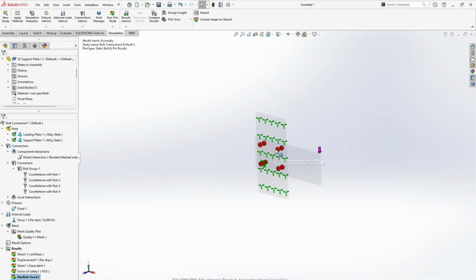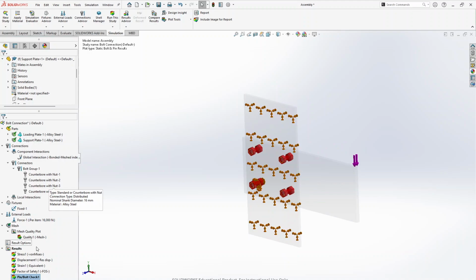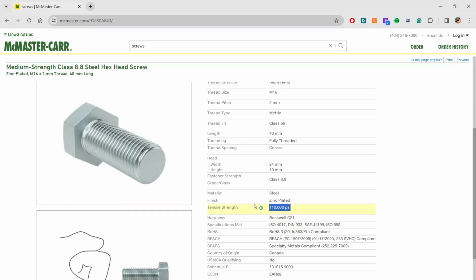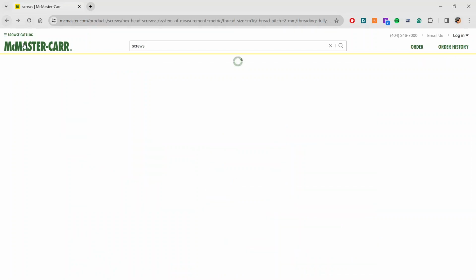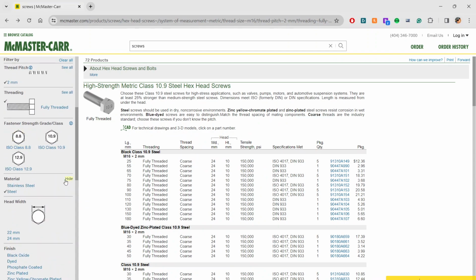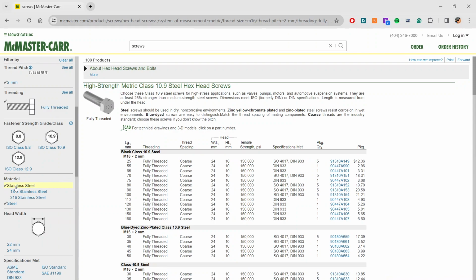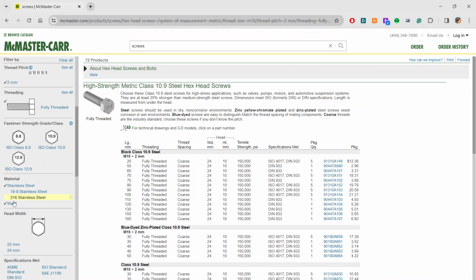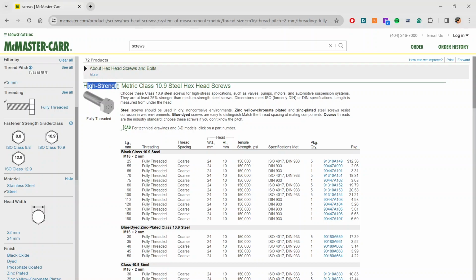I wanted to know what the solution is for that, as an engineer, if you wanted to provide a solution. For example, let's exercise the option of selecting a different material for this bolt. Instead of the current material, I will select the steel, but going with the highest strength. Same material but highest strength.